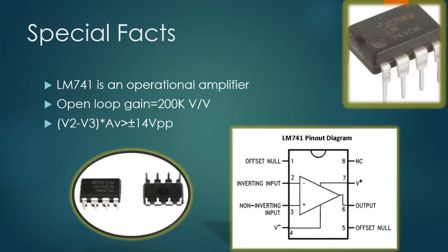Because of this gain, the difference of voltage input multiplied by gain exceeds the supply voltage, which is 30 volts peak to peak. This means that the voltage output is always in saturation, because the output of an amplifier can never exceed its supply voltage. So, in our digital oscilloscope, we are not going to see a sine output, but something that looks like a square sine.